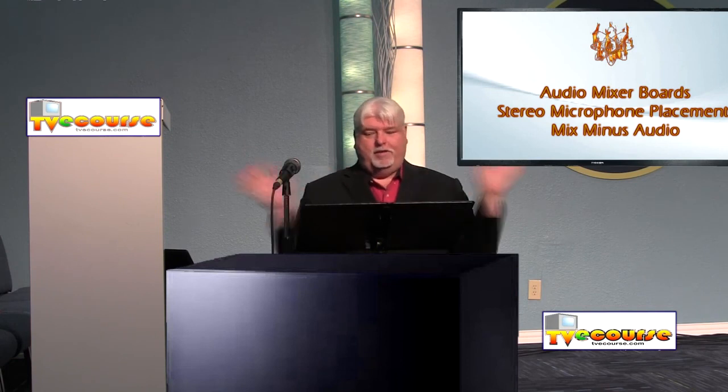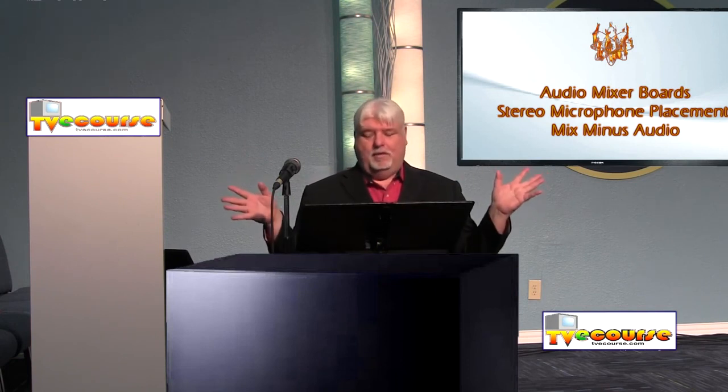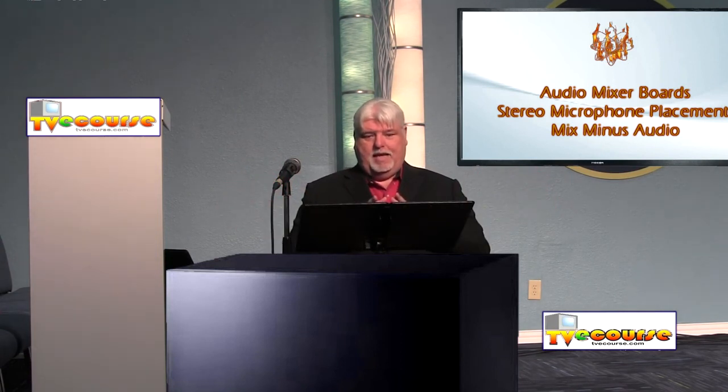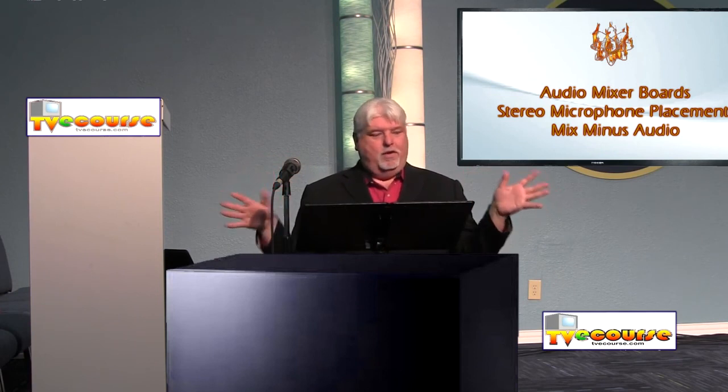If you hear something great in stereo, it's absolutely beautiful. It's got a lot of separation, but when you combine it back into mono, it has cancellation, and so the phase is out from the right to the left. When you combine the signals back together, it cancels, and you can have a situation where you hear beautiful stereo and someone listens on a mono monitor, mono radio or something, and nothing's there.